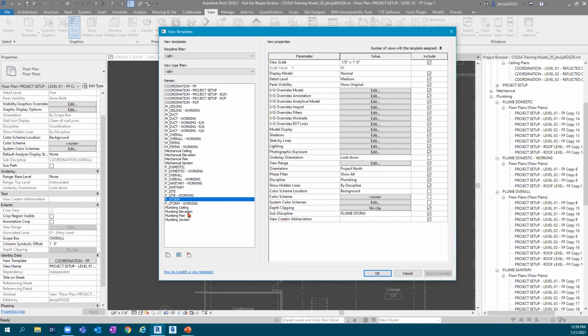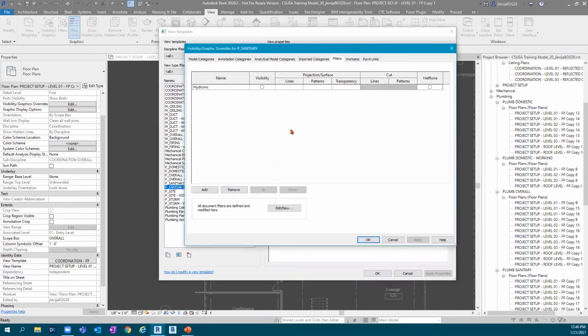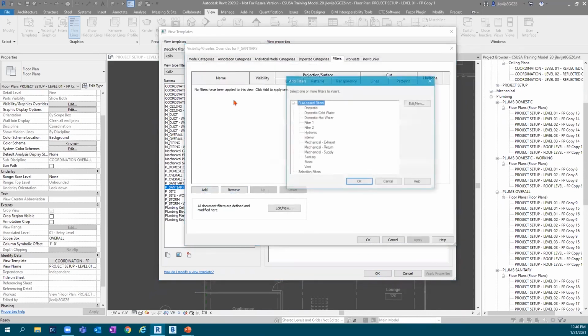By having these other options for view templates and their designated filters, when we have to make an adjustment, specifically elevation, when it comes to underground and getting around a footing, or piles, or getting underneath that mass bank of conduit, having these extra views and view templates, and the filters designated to that, allows us to go in, set up our crosshairs, and get our orthographic view in play.